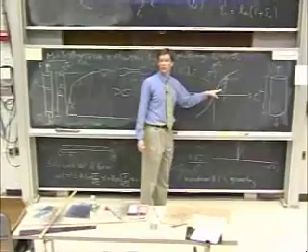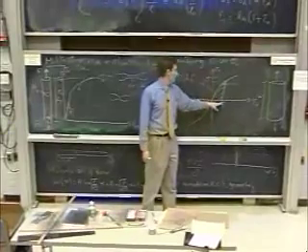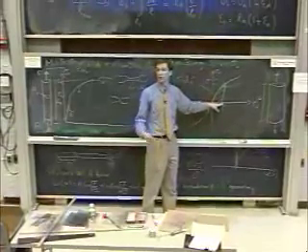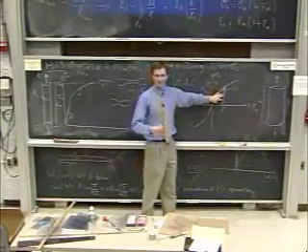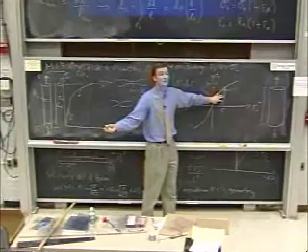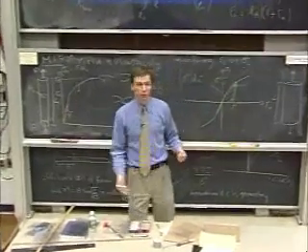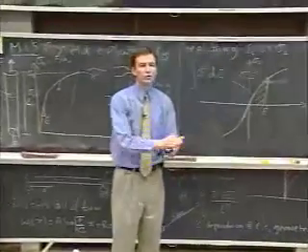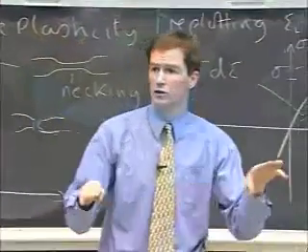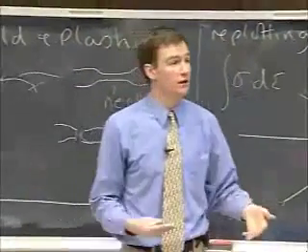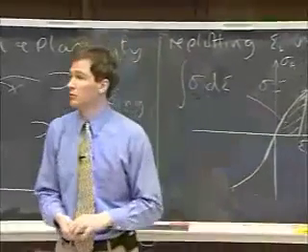And this is an irreversible process. Thermodynamically, unlike elasticity, which is reversible, with plasticity you're having to do work. It's being dissipated as heat. It's not recoverable. And this is why if you do a rolling operation, or just frictional contact between surfaces, which have lots of little asperities on the metal surfaces deforming plastically, the metal's going to heat up by this amount, depending on the thermal conductivity of the material.